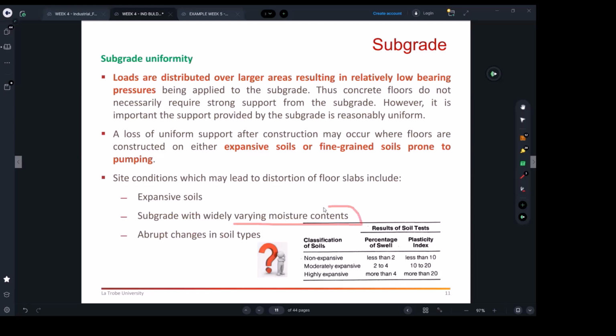Also, the moisture content can be an issue, but usually the geotech engineer will give you guidelines, and the document I was referring to will also give you processes on what to do. Sometimes a developer buys a site with a lot of trees. Trees suck the water from around their footings, and if you decide to take the trees away, you're going to change the moisture conditions. So sometimes you have to dry the ground.